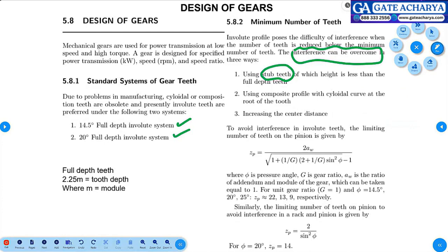Then only can you pull the vehicle for several revolutions. Take your two-wheeler: first gear, second gear, third gear. First gear is nothing but a smaller gear engaged to a bigger one. Second is more or less the same, and third the same. In the fourth, a larger gear is attached to a smaller gear, where you can give the entire power for conversion into speed, because torque has been pulled and inertia has been overcome.